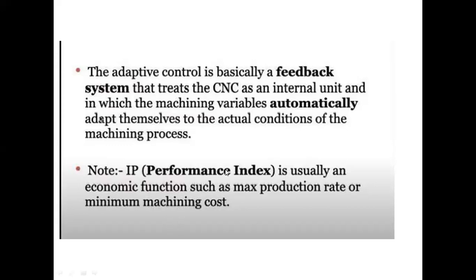IP is your performance index. We'll see what this performance index is. It is usually an economic function such as maximum production rate or minimum machining cost, right? These are basically the objectives, you can say. You want to have a maximum production rate or minimum machining cost, depending on what it is that you are trying to achieve.